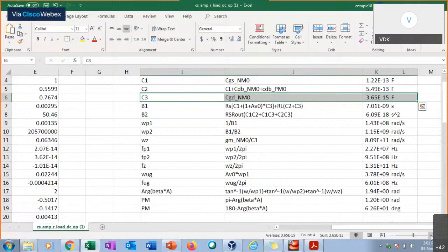All right, so I can express the overall transfer function gain for a two-pole transfer function amplifier as AV equal to AV naught, where AV naught is the small signal DC gain, multiplied by (1 minus S divided by omega z), brackets closed, with the RHP 0, then divided by the polynomial in S, which is in the form of 1 plus B1S plus B2S squared.